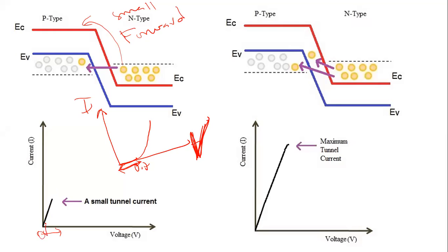Okay, so what current is that? That is actually the current due to tunneling of electrons. How does tunneling occur? You know that in order to have the usual IV characteristics, when you supply negative potential or negative energy to the free electrons here, the energy supplied from the external forward voltage has to be sufficient to climb over this potential barrier and jump to the P side here.